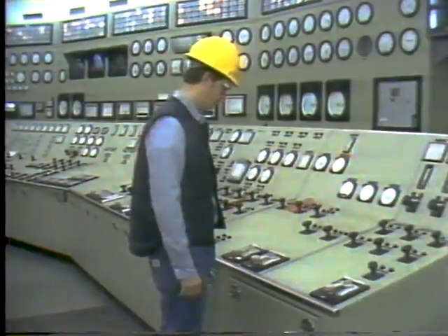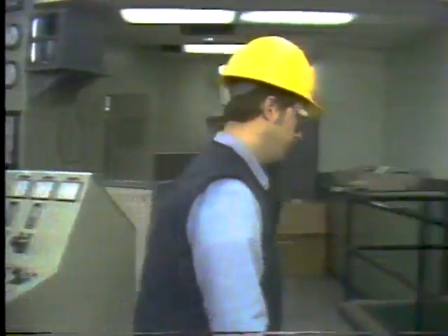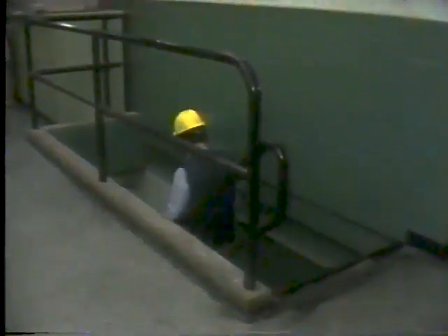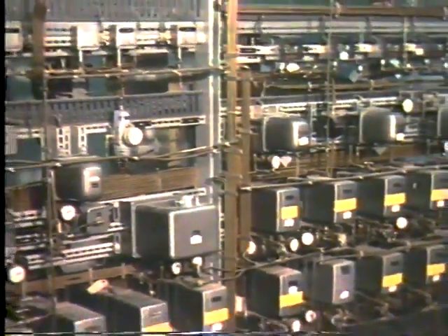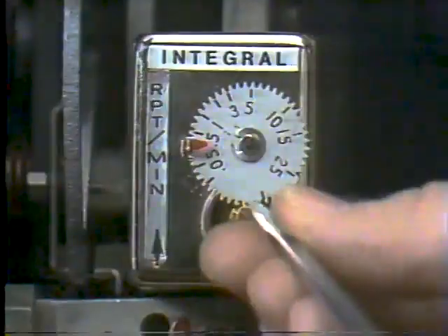Even a small amount of reset will cause a controlled variable to eventually return to set point. But what the technician wanted, and what you will want when you tune a system, is to get the controlled variable back to set point quickly, with minimum cycling, of course. So it was back to the controller again. This time, the technician decided to try a reset setting of 0.8. He'd learned that 0.2 was way too low. He knew that 1 was probably too high, so he figured 0.8 might be close.